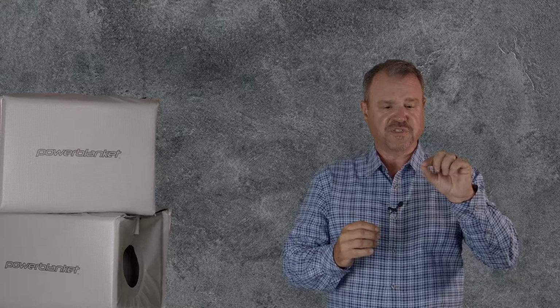Electric heating elements also have resistance to ground. That is, that there's a resistor suspended in the middle of a heating element. When that resistor actually touches the inside of the heating element, it'll short out. There's a way you can check to see if your heating element has potential to ground. It's called a megger. Meg-ohm resistance check is taking a meter that can go from about 1,000 to 5,000 volts DC. You apply it to the heating elements and you crank it up and you can see if you've got resistance to ground. In other words, megging your heating elements is probably one of the best ways to really check your heater to make sure that it's not going to short out on you.